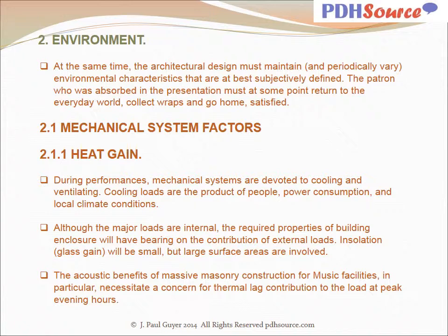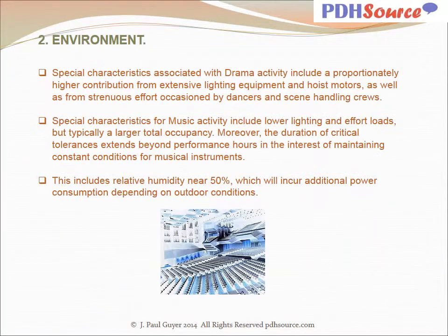With regard to mechanical systems and the question of heat gain during performances, mechanical systems are devoted to cooling and ventilating. Cooling loads are the product of people, power consumption, and local climate conditions. Although the major loads are internal, the required properties of building enclosure will have bearing on the contribution of external loads. Insulation and glass gain will be small, but large surface areas are involved. The acoustic benefits of massive masonry construction for music facilities in particular necessitate a concern for thermal lag contribution to the load at peak evening hours.